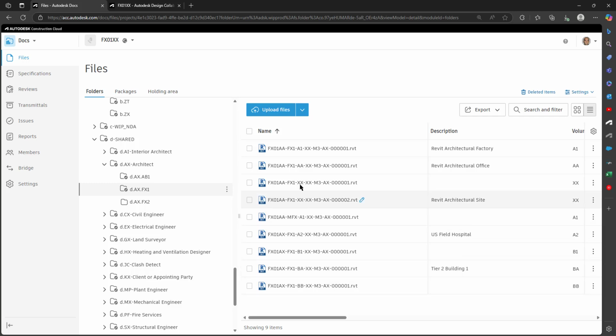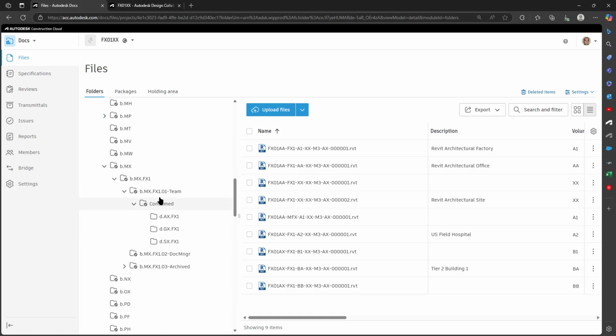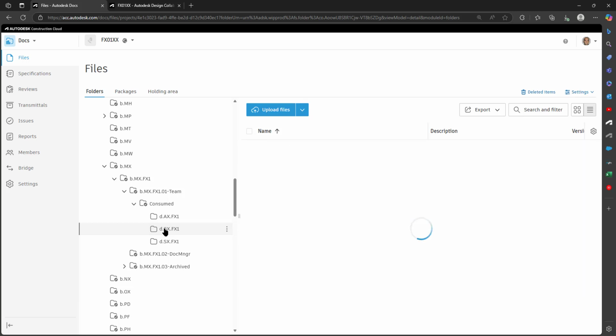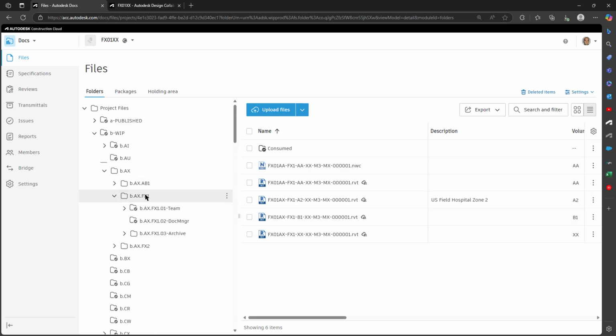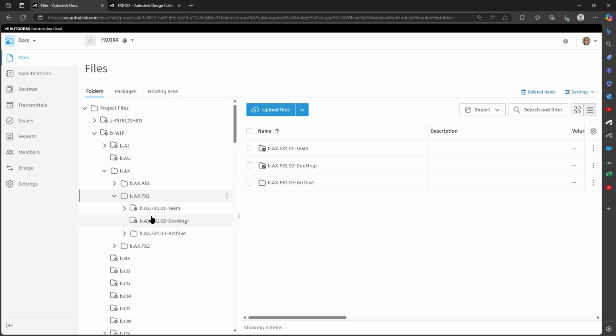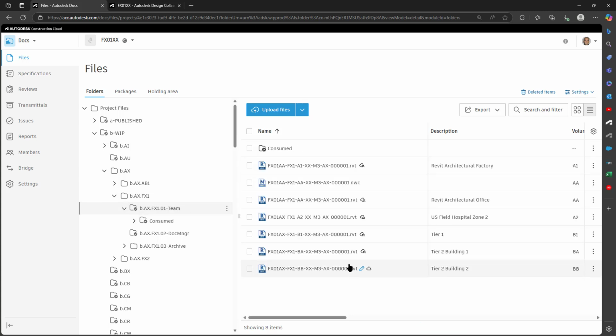And so once you've shared your packages with the first and the second tier links, or the second tier links being repathed within the first tier link, what you will do on the file that you are working with in your work in progress folder is to revert back to the links that point at the work in progress folder, not the shared folder. So there's a procedure to follow on sharing day where you change the link paths and then share your files with the other disciplines.